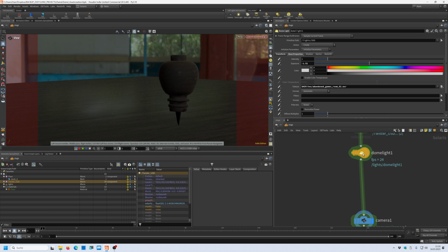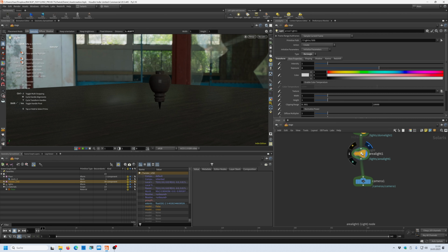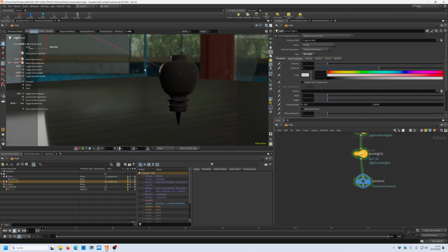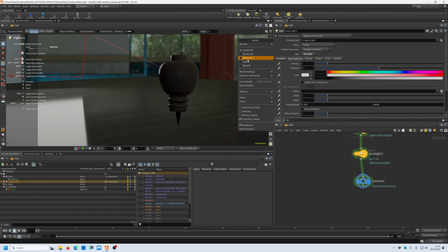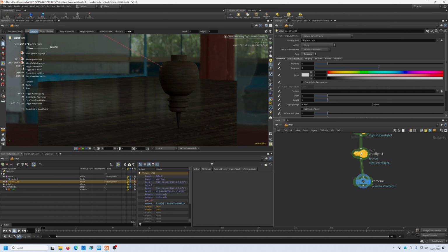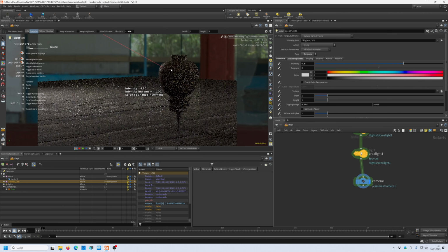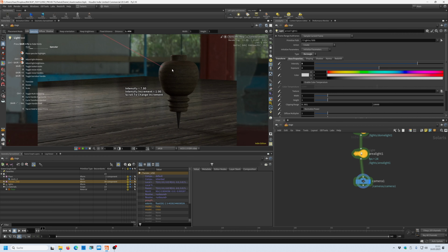The next thing I like to do is I create another light, an area light. So with this area light, I can specify where I want to point, specular, diffuse, and shadow. With this light selected, I can click on the light and I can point exactly on that point that I want to have this light. Okay, so now I can make this. Here you can see the shortcuts to change things. So what I like to do is I change the intensity of the light.